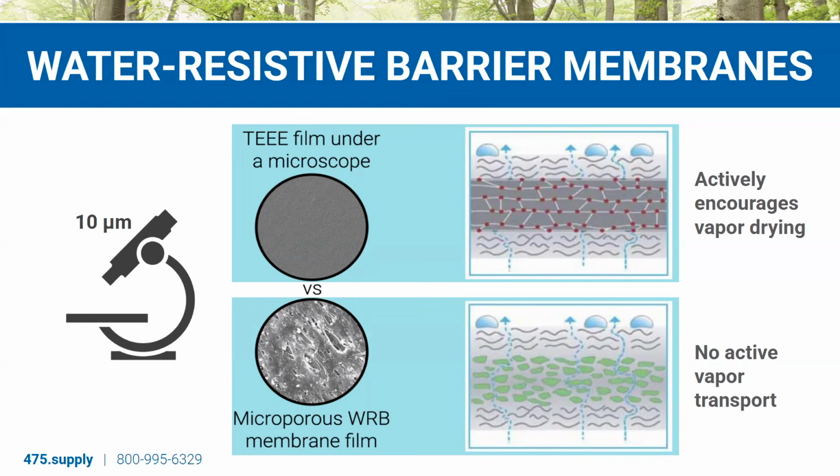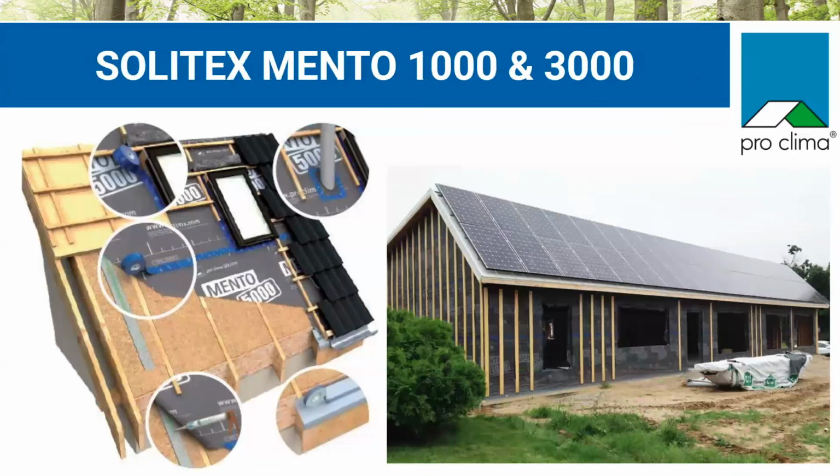So they tend to clog or deteriorate over time, and we don't have the robust watertightness or durability of the monolithic membranes. With these microporous membranes, the wood tannins of the siding or the framing can break down those pores. So we have a lot of durability and longevity issues with this older type of technology, but they can still be quite vapor open, which is a good thing for most of our climates.